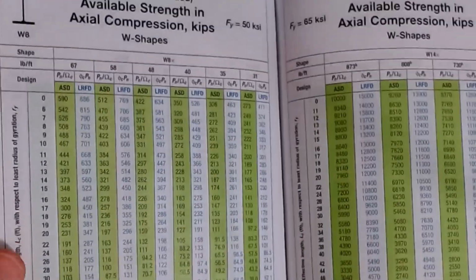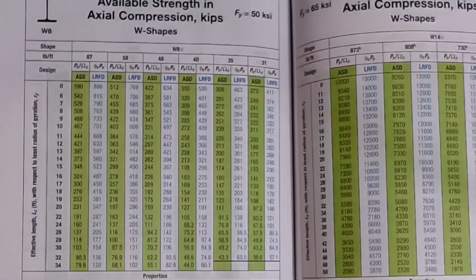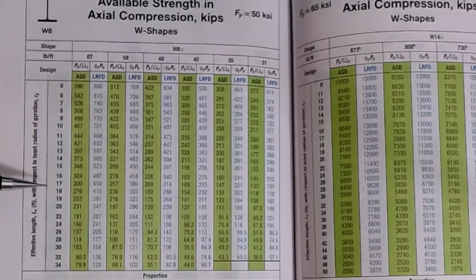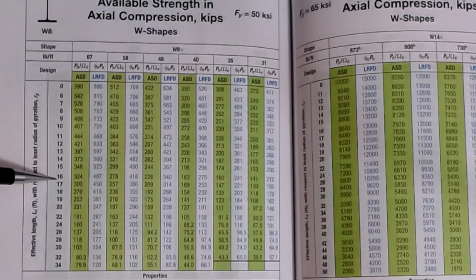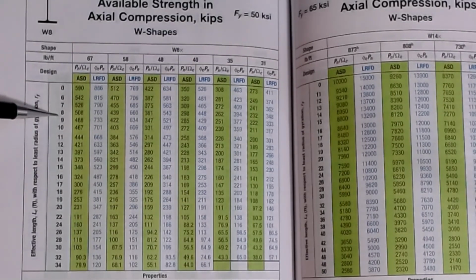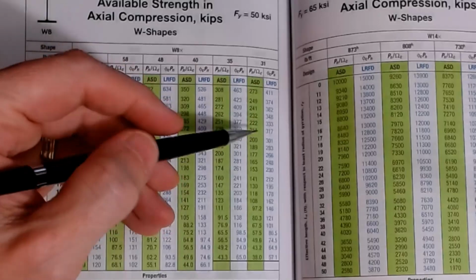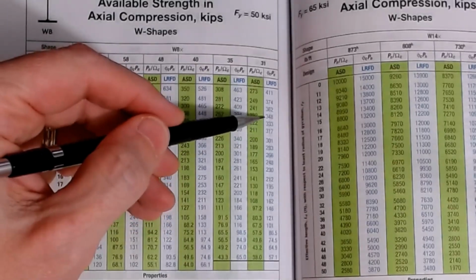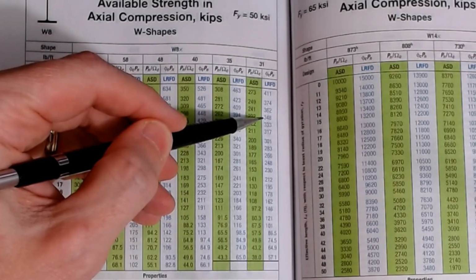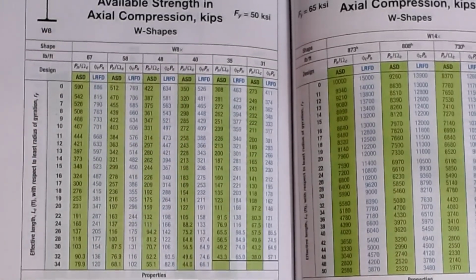We're going to size all of them in a similar fashion to how we did it in the last video. So if you need a review, go back and watch that video. We're going to go quickly through this process now that you know how to do it. Instead of being on the 16 line, I'm now on the 8 line, and I'm looking for 274 kips minimum. If I tick all the way over to 18, the smallest number I get on the 8-foot line is this 348 at a W8x31. So it's significantly over designed even at that.